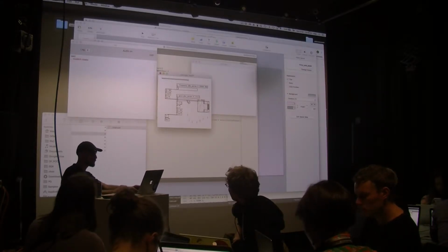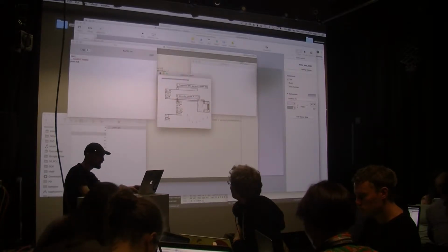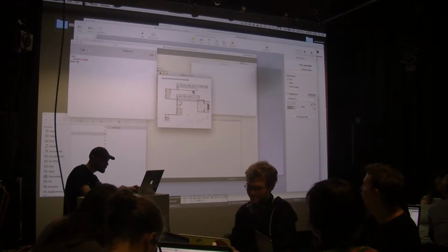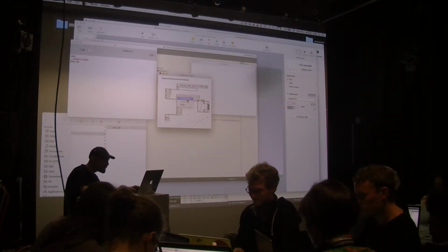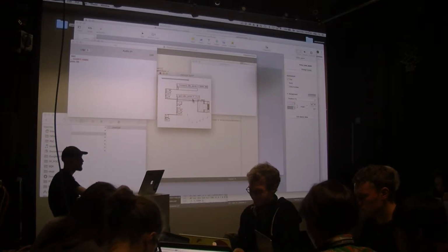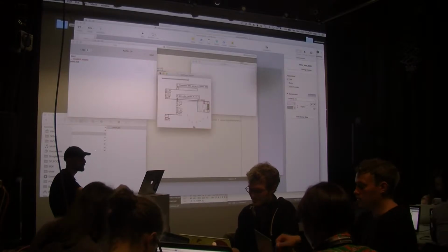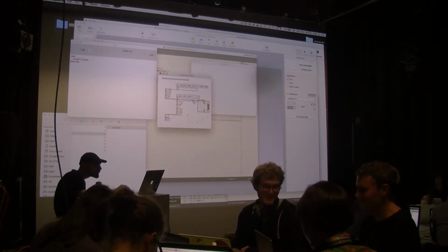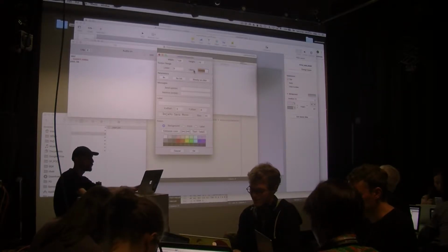The gain slider is set to 0 to 20,000 instead of 0 to 1, because I copy and pasted this slider, which is 0 to 20,000. So the way to fix that is if you right-click, go on Properties, and change the upper range to 1.